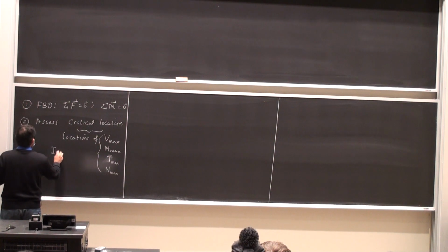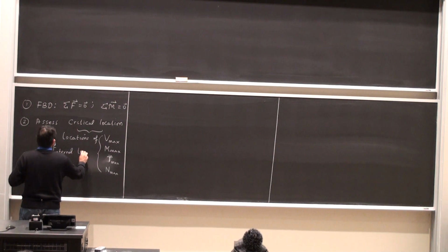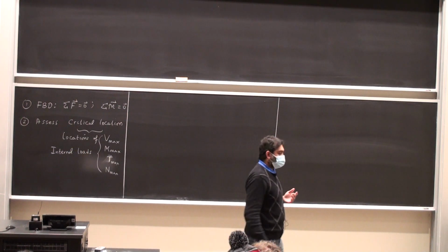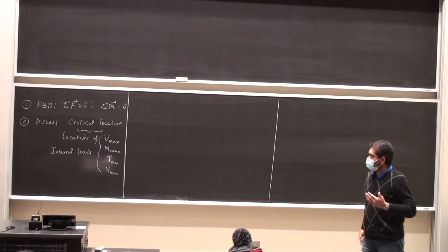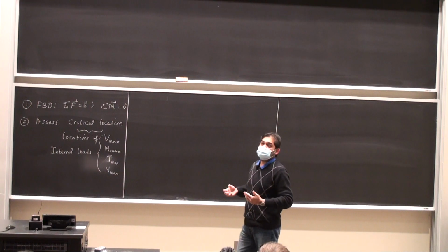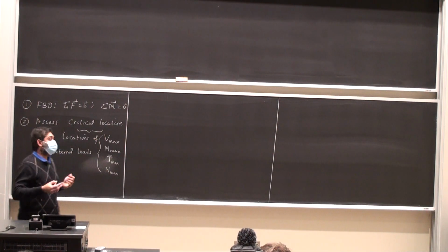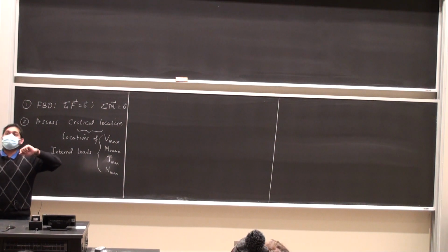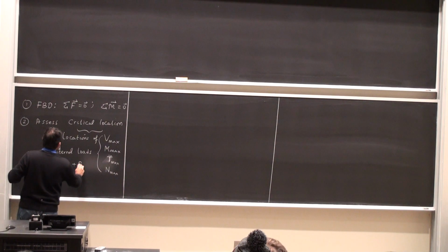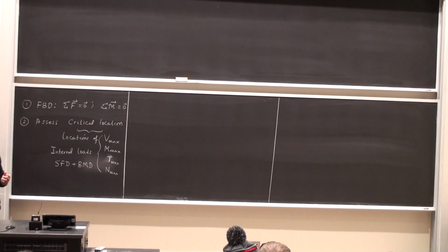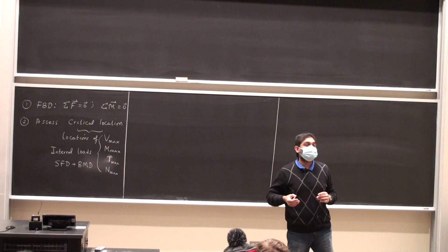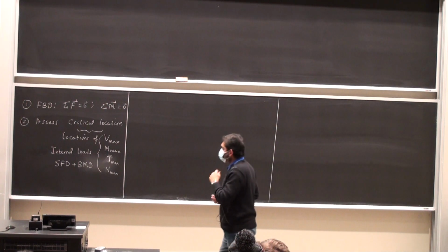Okay, so these are all internal loads. In many problems you can inspect it and do it, but in most problems you have to do it step by step. When we did problems in torsion, we had to section it between every two discontinuities and figure out, okay, here is where the internal torque is the maximum. If you're doing problems on forces such as Vmax and Mmax, you have to draw the shear force and bending moment diagram. If you have axial forces, you can inspect by sectioning off between every two discontinuities to see where the largest axial force is. Okay, so those are all things that we typically do.